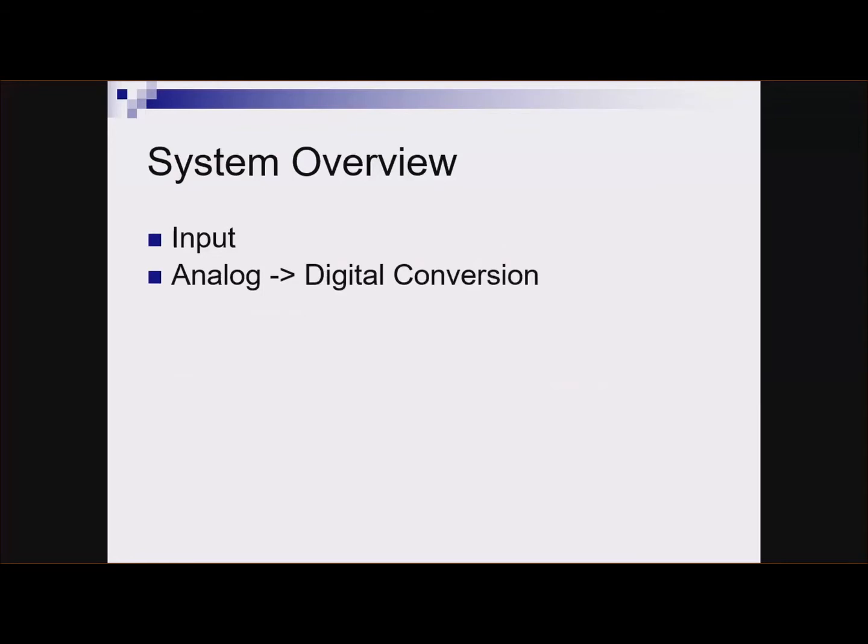Sometimes things are fed into a computer in a format that the computer cannot work with. For example, we saw in last week's lab, and we saw this week in the shop, a little bit about potentiometers and thermistors. And what we saw is that the voltage level coming out of those can vary, almost infinitely, between 0 and 5 volts. So a computer can't handle an analog voltage like that. It needs to be converted into something the computer can deal with.